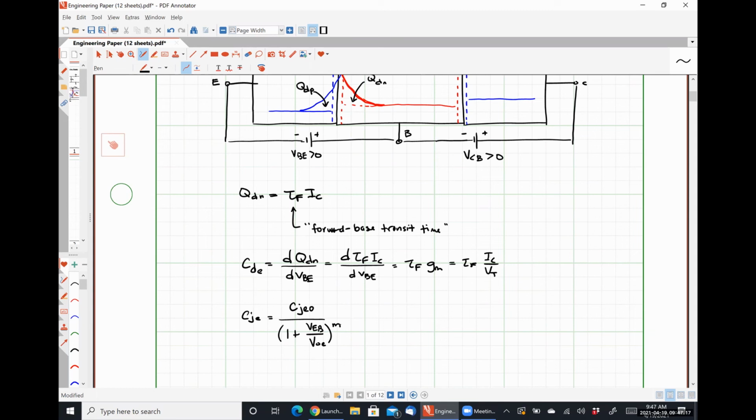All right. So one thing that we need to point out here, okay, this is a forward bias junction. This equation still works, but what should we expect to happen because it's a forward bias junction? We're making the plates of that parallel plate capacitor closer together, right?